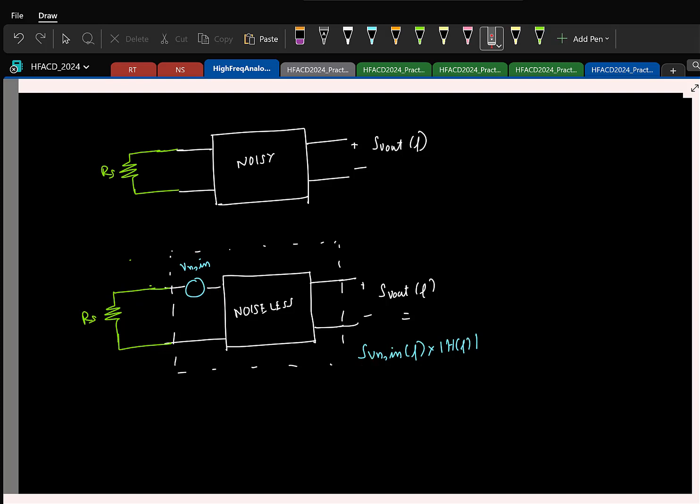Now you see that this voltage will get divided between the source resistance Rs and whatever Zin I have here, right? So let us say I take a case where my Rs is much greater than the input impedance, or for this I'll take Rs tending to infinity. Fine.